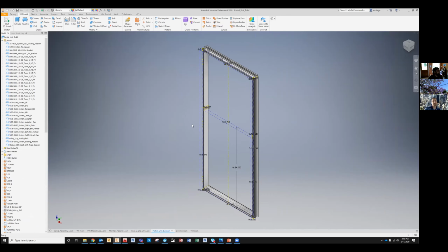So typically with Inventor, you create a sketch and then you would extrude that. You can create blocks within Inventor, kind of like the AutoCAD blocks. And so what we do is take our AutoCAD profiles of the dies and create sketch blocks in Inventor of those profiles so that we don't have to constantly sketch them in here or drag them from the AutoCAD drawings.